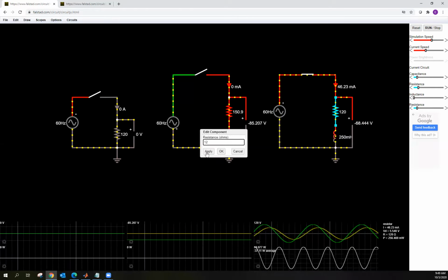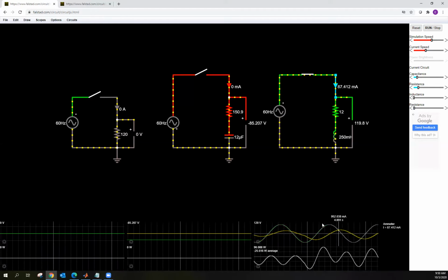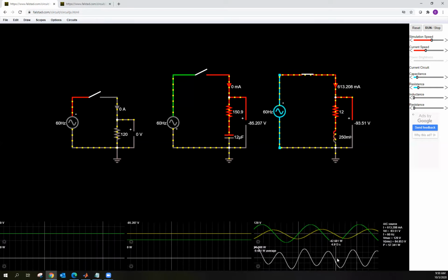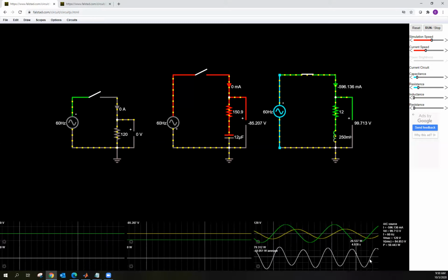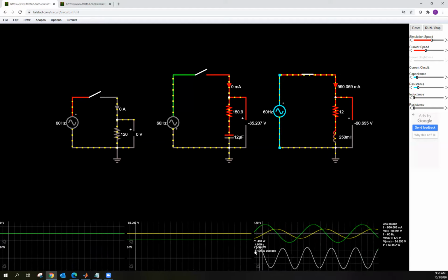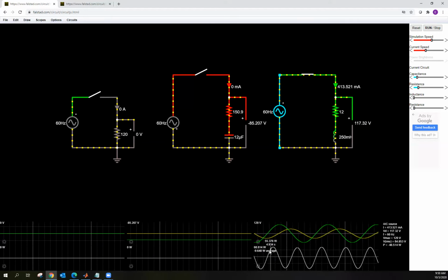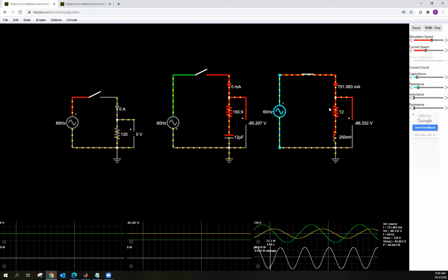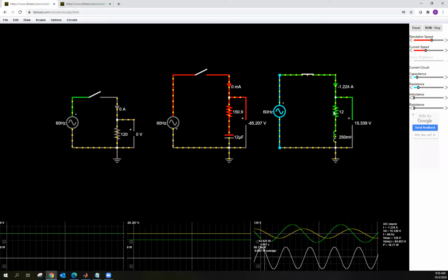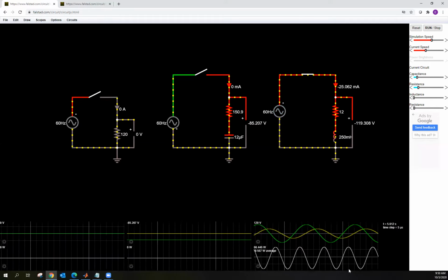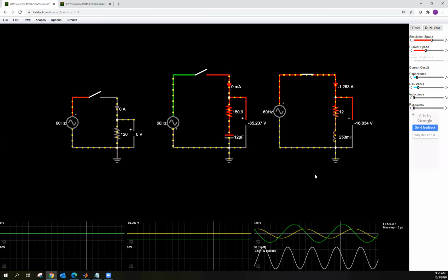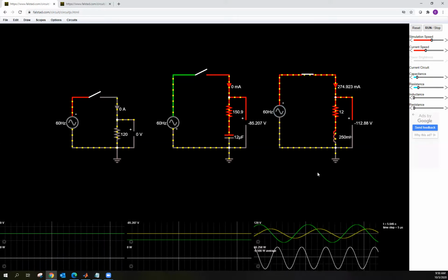Okay, and you can see, look at the yellow. The yellow current now lags the green voltage by nearly 90 degrees. And look at the instantaneous power. Look how after it settles out, it starts oscillating nearly about 0 watts, right? And so you can see that the wattage in the average definitely decreased from before, okay? We still have some resistance, so it's not zero, so you still have 9 watts burning off in this 12 ohm resistor, but notice how it shifted up. So the P now is very small, and I would say the power triangle is looking close to vertical with a slight angle forward, okay?